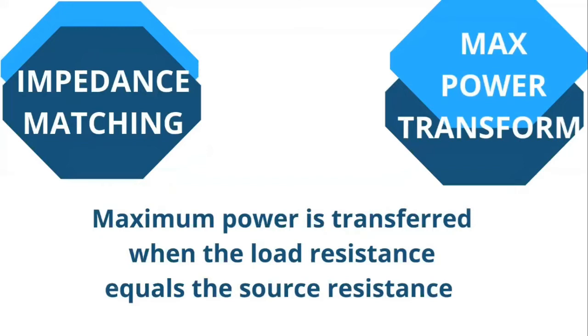Okay, now impedance matching. Again, you have studied impedance matching and the maximum power transfer theorem. All of those are interrelated. What is being said in this slide is that maximum power is transferred when the load resistance equals the source resistance. This is what is called the maximum power transfer theorem.